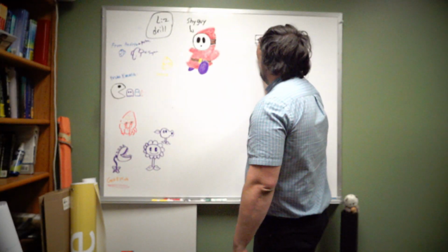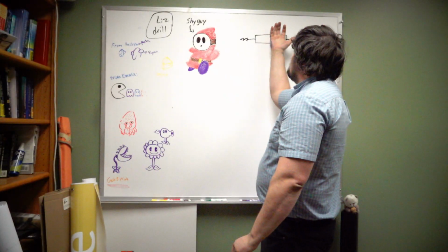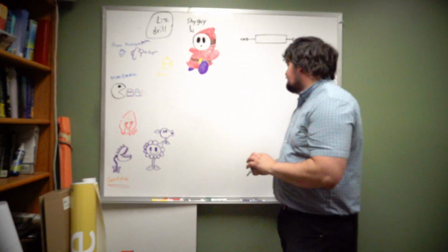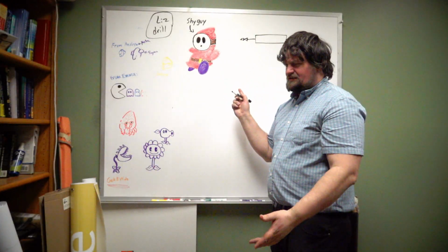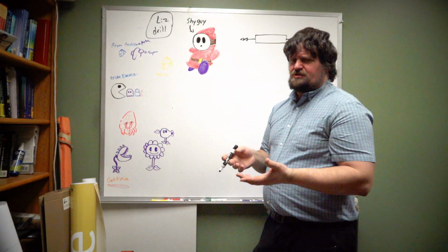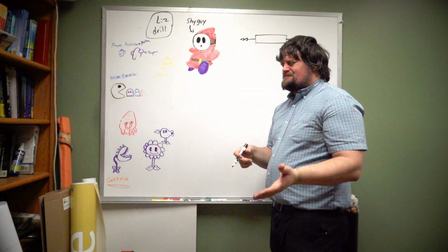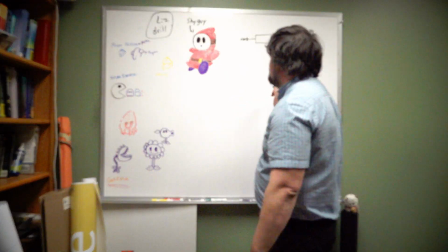And the way that we do that is we have a double-ended arrow. Now here, the double-ended arrow indicates direction using the right-hand rule, so you would expect it to torque in this direction on this side, and then it's torquing in the opposite direction on that side. So those two are going to be balanced. Okay. Now, when we're looking at this, oftentimes you're only going to evaluate torsion on a circular interface or on a hollow circular interface, because the torsional stresses get a little weird in a rectangular shape. It doesn't quite follow the equations that we have.